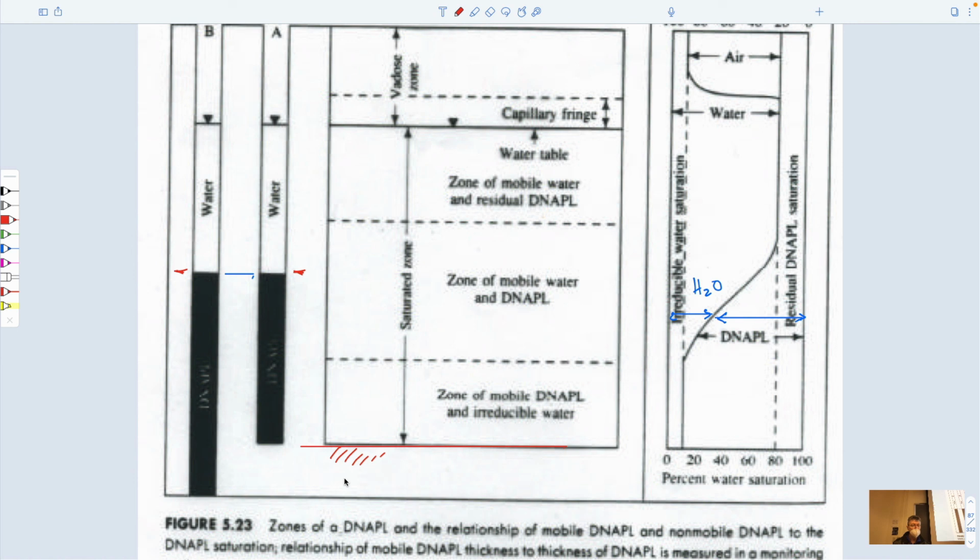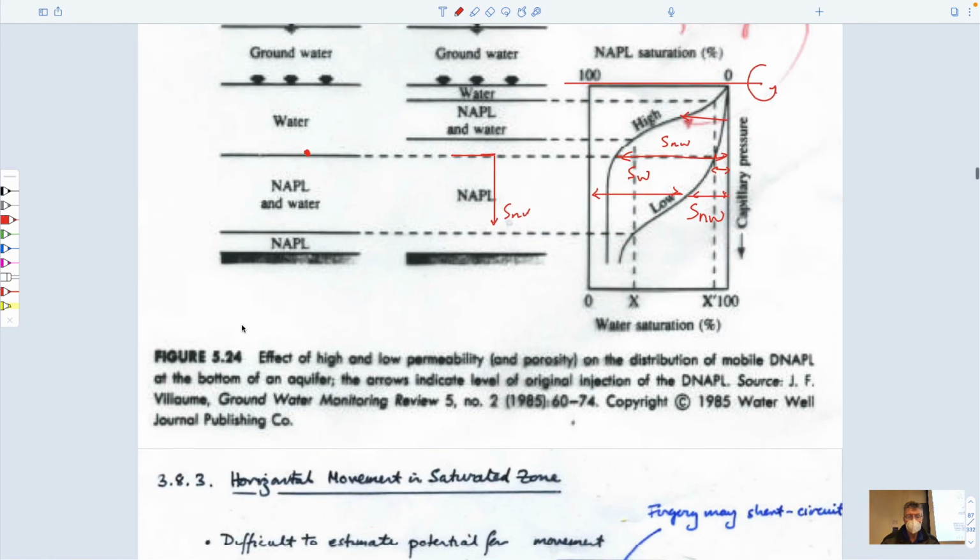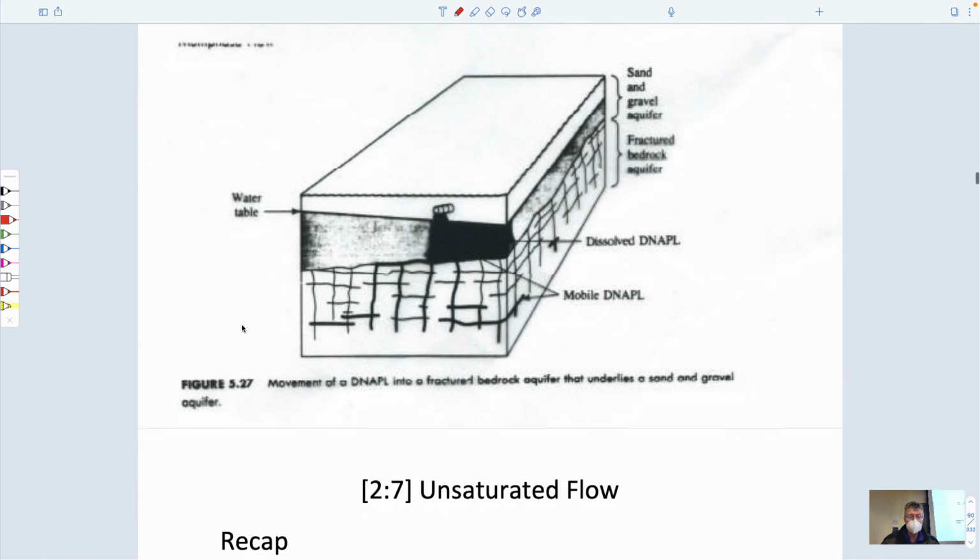higher depth. And so, different from the case of LNAPLs, where you get a depth in the borehole which also seems deeper than the true thickness in the aquifer is. In these cases also, you end up with a thickness apparent within the borehole which could actually be much larger than what is present, because you don't know anything about where the capillary barriers might be placed within the subsurface that would stop that fluid from going down. And I think that's all I really wanted to say in this.